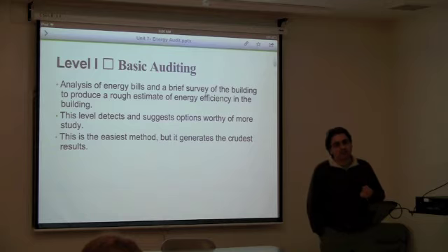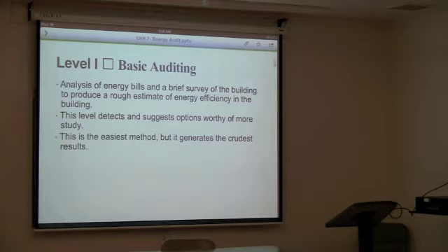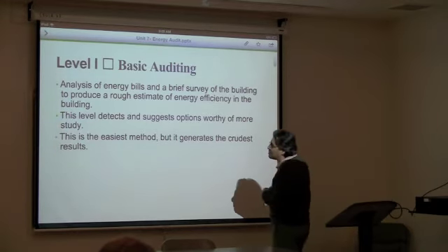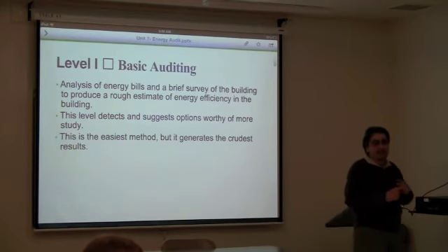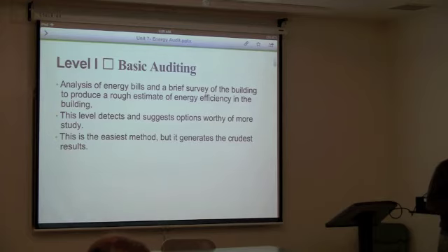And when you look at the bill, you usually look at 24 months, 2 years. And don't just look at the bills and go page by page. If you have an Excel sheet, draw it based on month, look at the fluctuation, how it changes. You have to be able to create a pattern between the fluctuation of the energy. Most likely the energy usage in a facility is not going to be constant. If it's an industrial facility, depending on the load and production, the energy is going to be more or less. If it's a residential facility, depending on the time of the year, summer, winter, your bill is going to be different.